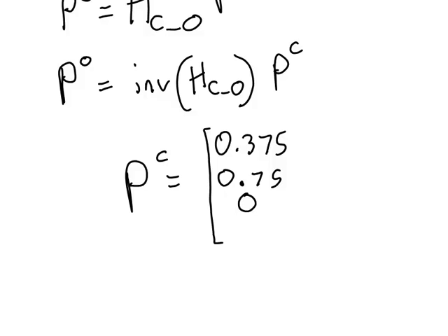Finally, to find the value of a point, in order to use it in a coordinate transformation, we always have to stick a 1 down at the end so that the matrix multiplication will work. We can now take this point in the camera frame, multiply it by the inverse of the homogeneous transformation matrix that we found, and find the location of that point in the base frame.